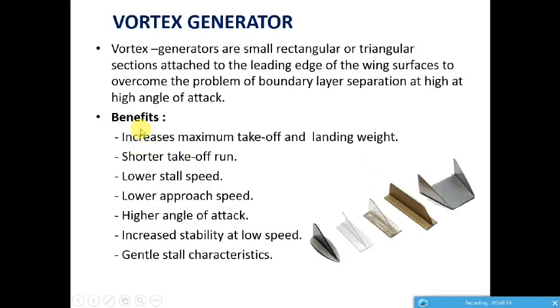So these are some of the benefits: increased maximum takeoff and landing weight, shorter takeoff runway, lower stall speeds, low approach speed, high angle of attack, increased stability at low speed, and gentle stall characteristics.